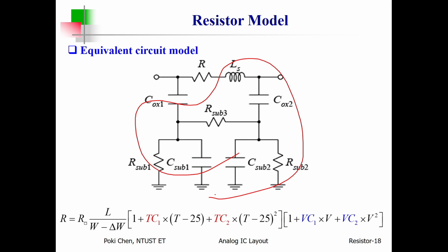If you have a wrong or bad layout pattern, you will induce a lot of parasitics for your resistor. The overall performance will be substantially reduced. So please have a very good, very neat layout to reduce the parasitics.